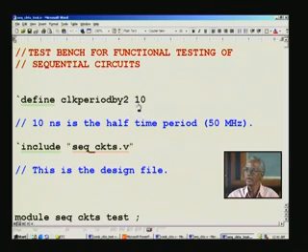So, this implies there must be a time scale definition also, and your compiler may give a warning, but you can overrule that warning, and you do not have to put time scale every time, right. You have already taken it into account in the test bench. So, you need the time scale only for the simulation.